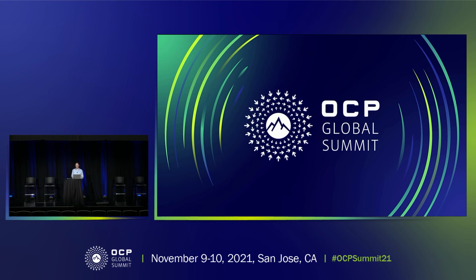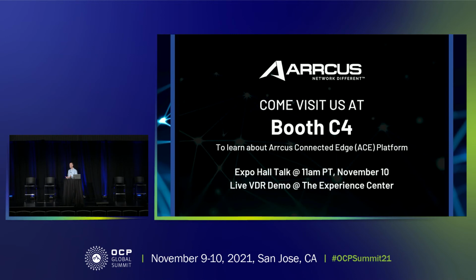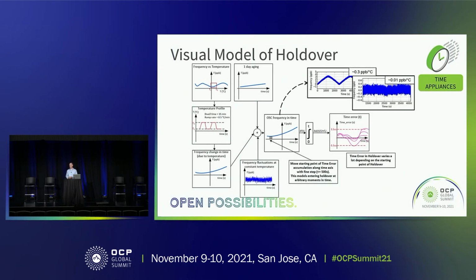Yeah, there are differences between the different types of oscillators, but where they would show up in this model is you'll be trading off different subcomponents, different noise components. And while those noise components will change the way that you add them, as long as they're following a Gaussian distribution, which we're assuming they are, then it'll just show up in the numbers, as you said. Yes, definitely the way that they add up should all be consistent.